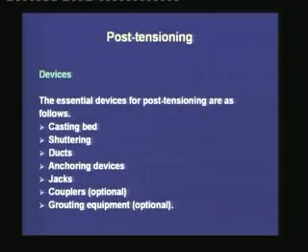Next, we shall move on to the devices that are used for post-tensioning. Just to recollect, in the pre-tensioning, we had seen that the main devices were a pre-stressing bed, the end abutments with appropriate foundations, then we needed some jacks, and then we had to have some cutters for the tendons, and if we avoid a pre-stressing bed with end abutments, then we need some sort of stress bench which is a self-equilibrating system.